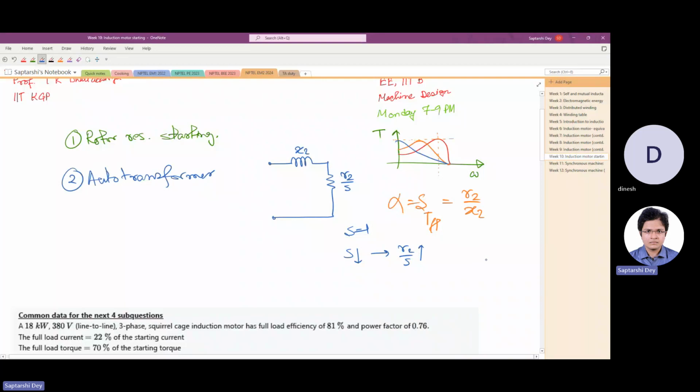Obviously they are inferior, because if you put resistance in series, your overall efficiency reduces, and if you put an inductor in series, your efficiency is not reducing, but your power factor is reducing. Reduction of power factor actually leads to reduced efficiency, because you are drawing large current, but you are not getting that much active power. So that is in one way also a reduced efficiency.